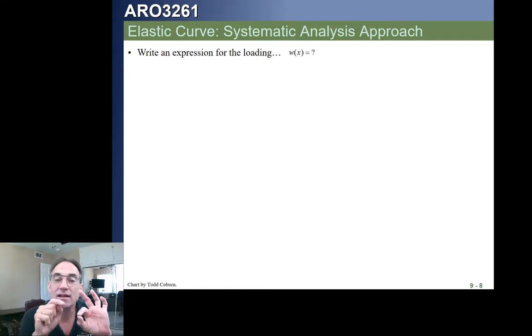Find each and every imposed load. First we've gone and drawn a free body diagram of the beam. We have removed any constraints and replaced them with the forces and/or moments that they can translate into the beam. We then are going to write a singularity function term for each and every load moving from left to right, for every force, every distributed load, and every moment. We might have to first characterize our loading so that each term appears in that table. We'll look at that a little more again today. We looked at that last time a little bit.